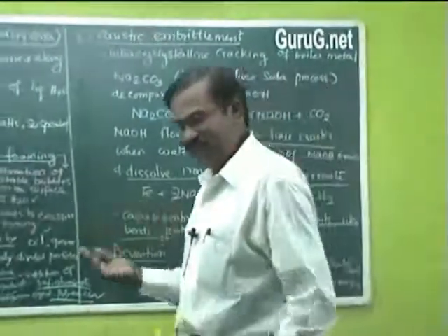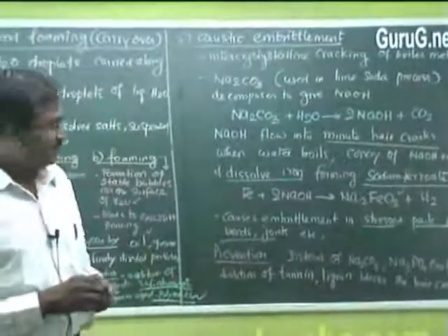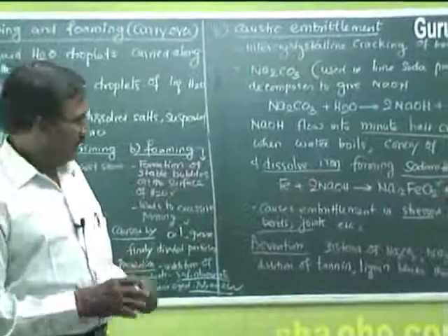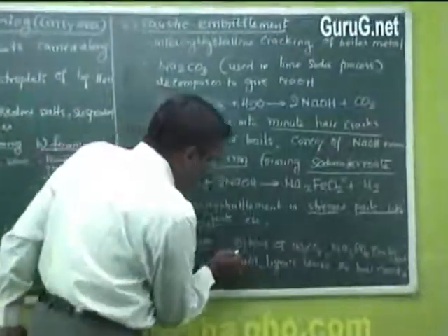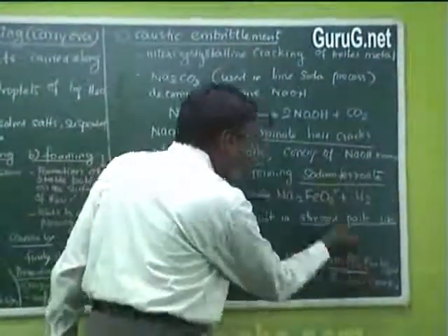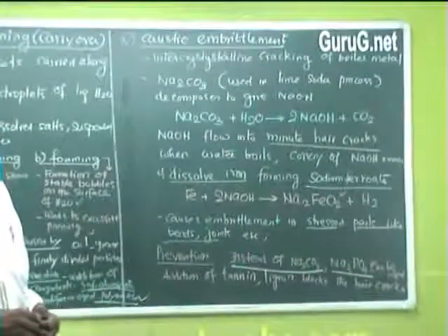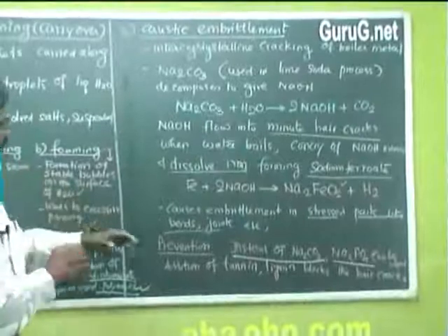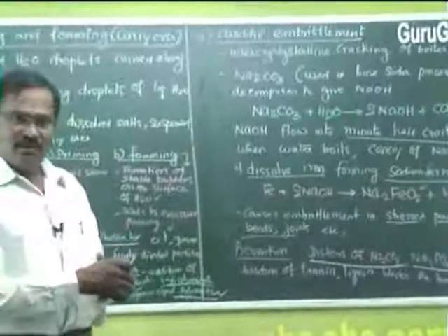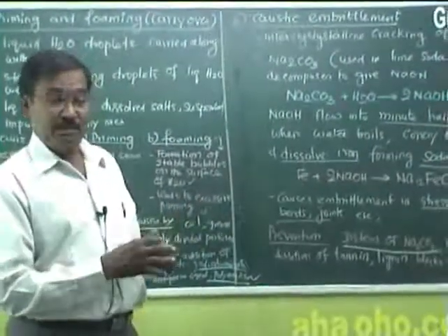So very simple. Since you are having sodium carbonate, there is caustic embrittlement. In case there is no sodium carbonate, there will not be any such thing. So keeping that in mind, instead of sodium carbonate, we are adding sodium phosphate during the lime soda process. That is one thing. And another thing, only when there is some minute hair crack can the sodium hydroxide, if any is formed, go into it. So avoid those hair cracks, but that may not be possible.